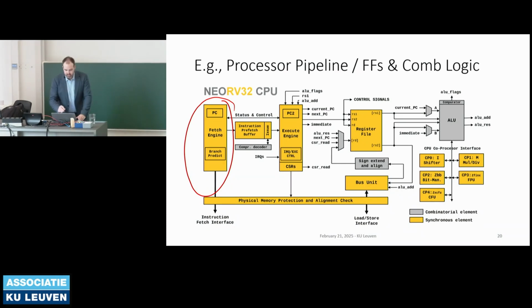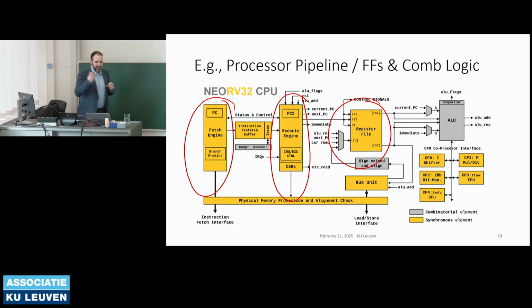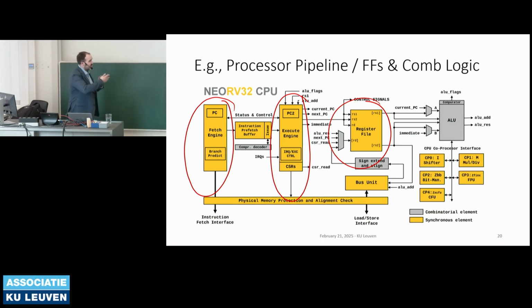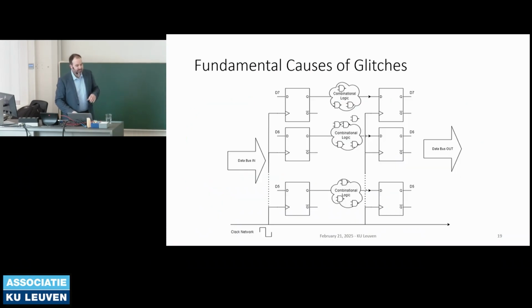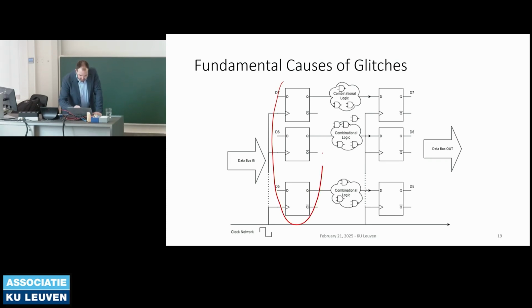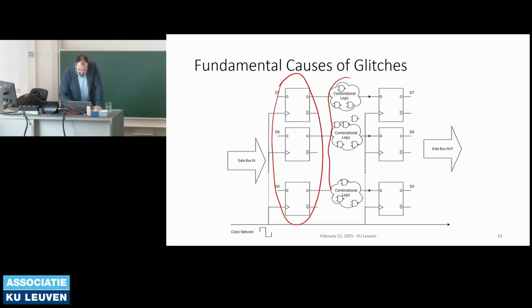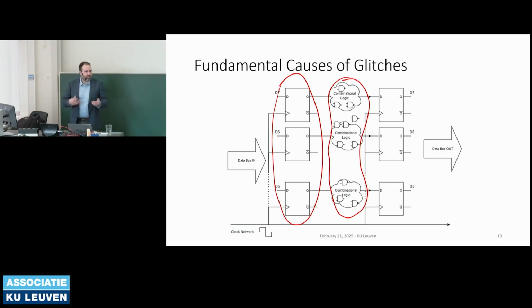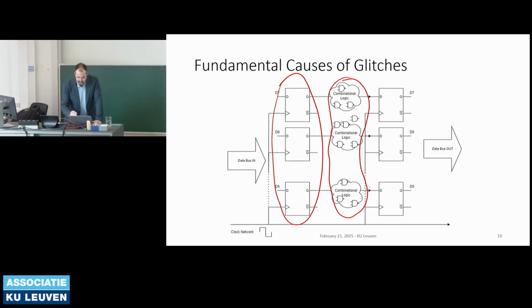It's going to take that instruction, execute it, and write data to internal registers, states, and things like that. So you have all of these sequences. Between all of these sequences, we have a bunch of flip-flops like this. So we have flip-flops, and we have combinational logic, which is all the logic that implements these functions, implements the ALU, implements decoding, whatnot.